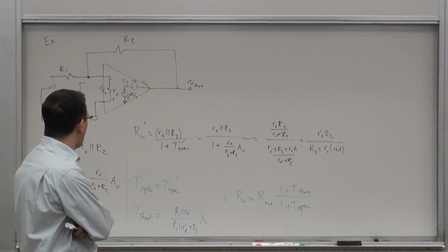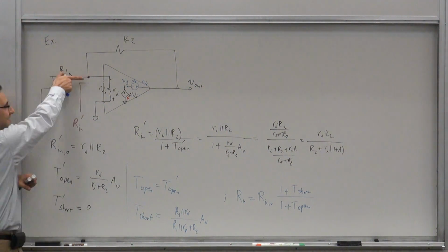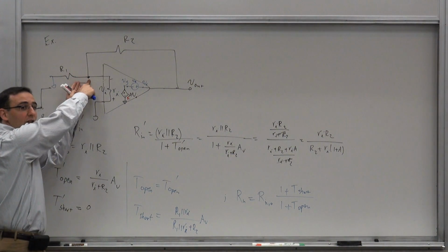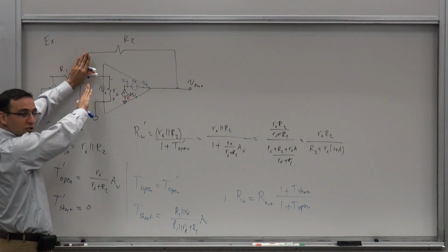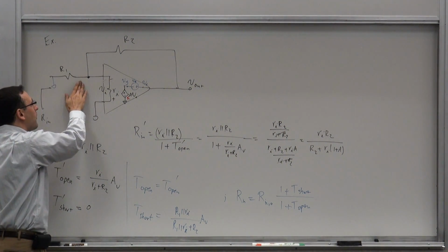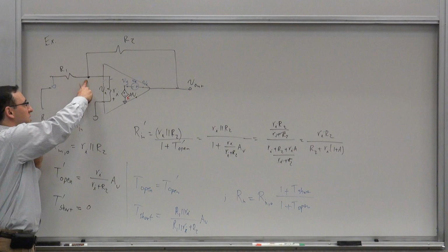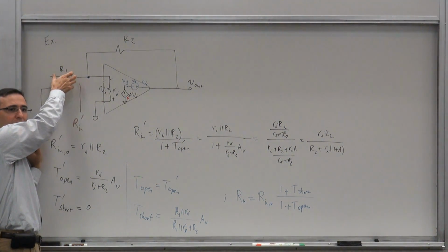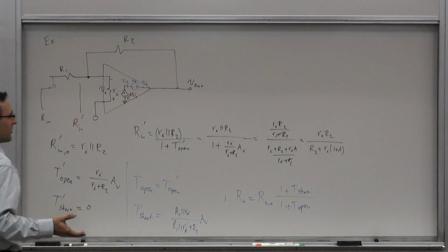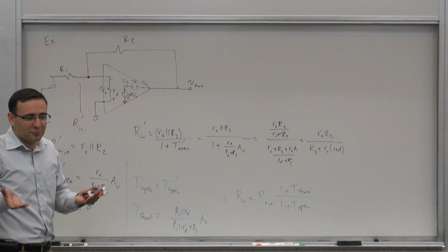And if you think about it, well, this is the series, right? I mean, this is another element of series. Still, from this point's perspective, it's shunt. So we still refer to it as shunt, right? But what I'm saying is that it's not an ideal, perfect, clear shunt from this point. If I have other stuff attached to it, it's shunt plus some other things. It's still called a shunt. But sometimes when there's too much of this kind of stuff, there's something called the bridge feedback, or bridge configuration, which is neither shunt nor series. It's just like, which one is it?